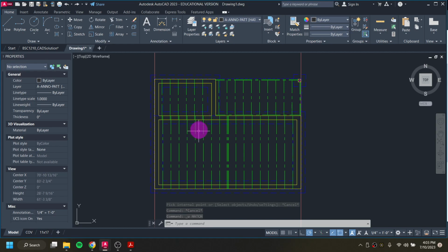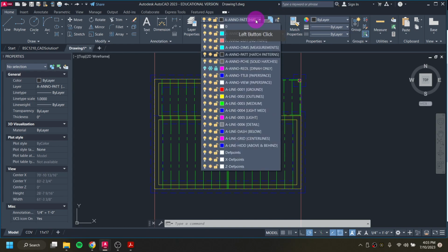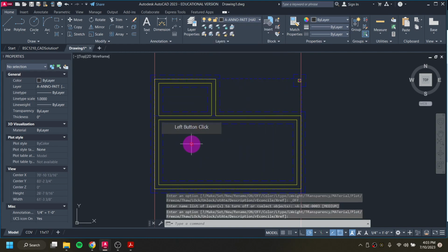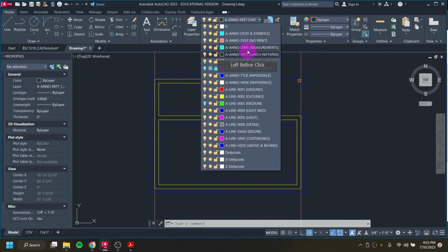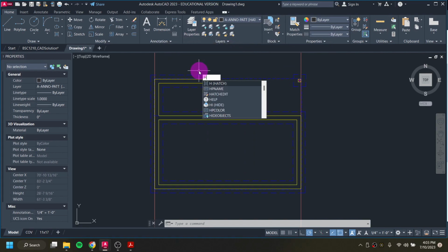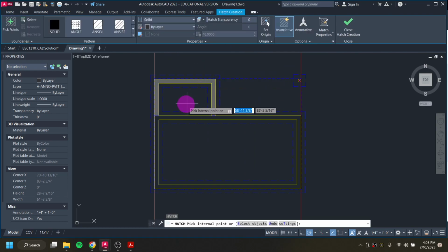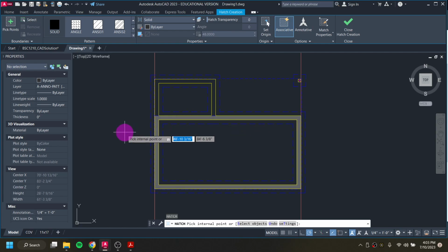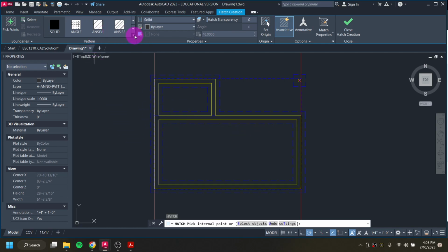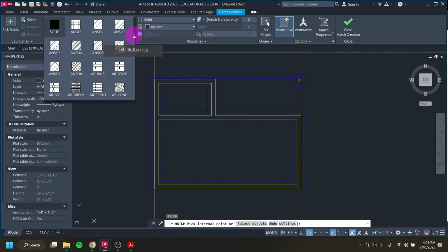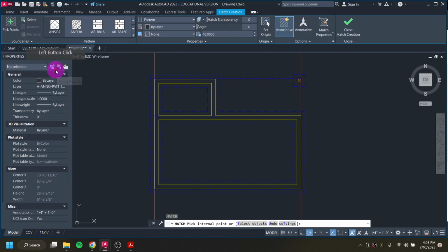What's going to make it easier is if I just turn all of these girders off for the time being. So I'm going to go into my layer properties, and I'm going to turn the light bulb for this line 3, for this green layer, and just turn it off. What that's going to allow me to do is, while I'm in my layer, AutoCAD, and I go into my hatch tool, I essentially have to click twice instead of clicking 70 times.